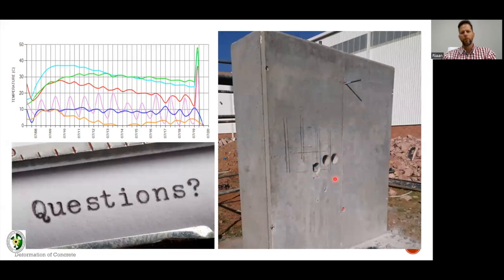Why did they do 3 core drills? So the laboratory was tasked to check, listen guys, are we going to achieve the 100 MPa? And they came at 7 days to core drill and then test the actual core for in-situ concrete strength, the actual strength. So now we are checking, did the hydration process desiccate? Did it overtemp? Were the temperatures too high? Maybe it stopped. Did something go wrong in the concrete?